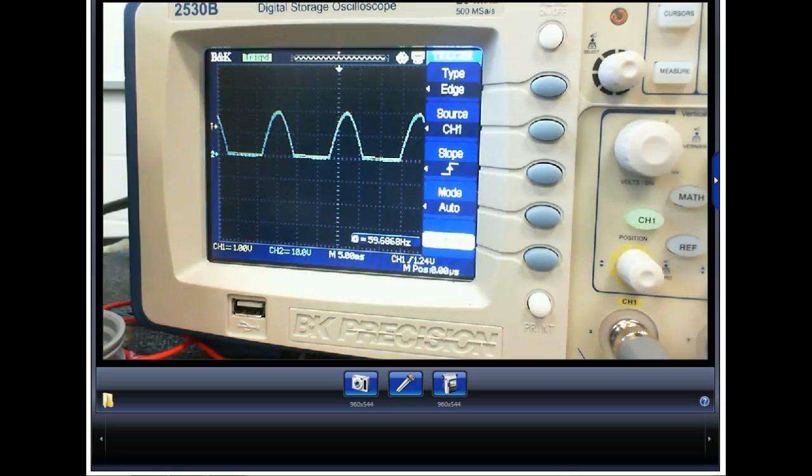It's stationary. So even when they throw the sign up on your TV and it stays up there for 5 minutes, it's a different picture each time. It's just doing it, and it stays. Every picture is exactly the same thing. And the TV is synchronized with the picture, by the way. So when they transmit video like that, your TV has no idea when to do the picture. So they send what we call sync pulses with the video. When I start a picture, they send a sync pulse, and then your TV picks up the sync pulse, and now your picture is in sync with what is being transmitted.